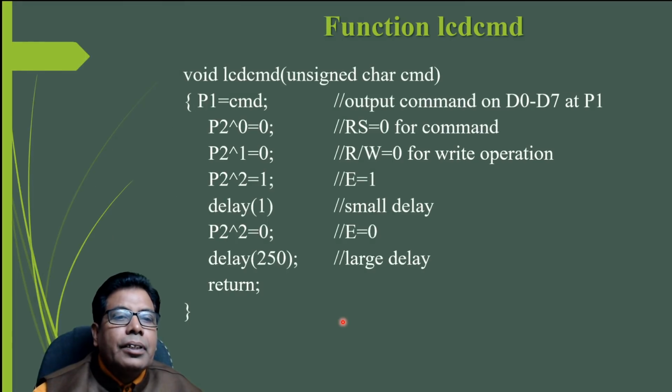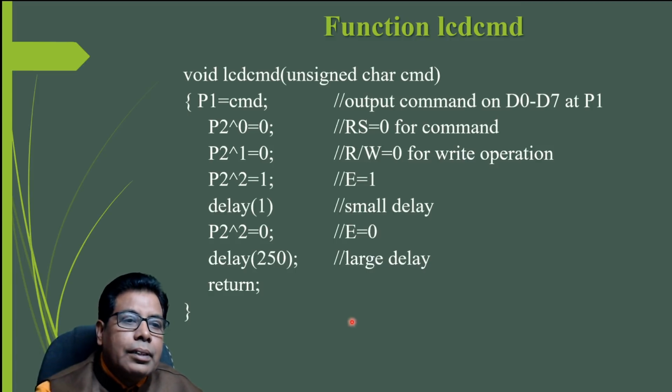Then let us go to the LCD command. Now this is similar to the command write. The name of the function is void LCD command, CMD. Here we'll be passing unsigned character command. Instead of data we are passing command here.